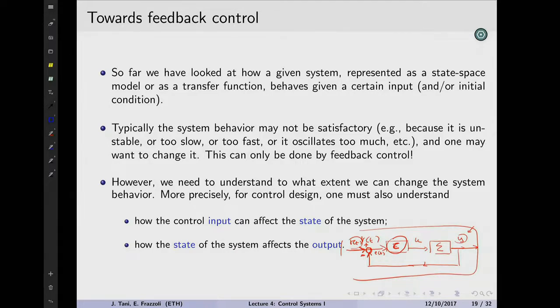That is, whatever you're given, whatever system you're trying to control, whatever its eigenvalue is, now we know that the eigenvalues tell us everything about the evolution of the system, we can arbitrarily cancel their eigenvalues and put other ones of our desire. So imagine that you're a control system engineer, you want to get a response of a system that has some specified properties. It doesn't oscillate, it goes fast enough, slow enough, whatever it is that you desire.